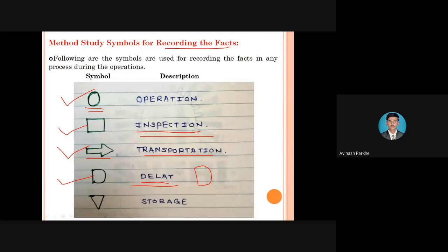Or sometimes, if you take the example of a lathe machine, whatever tool is provided to you on the lathe machine, by using that tool we can perform the facing operation, we can perform the turning operations, we are performing the chamfering operations. But if I have to perform the threading operation, what do I have to do?